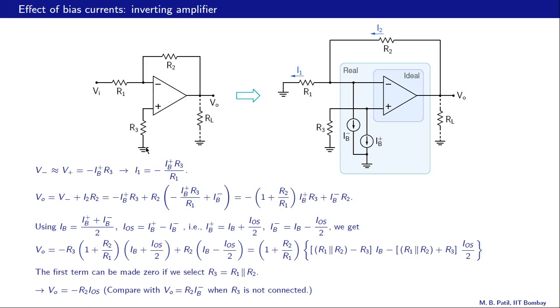We had connected directly the non-inverting input to the ground. So this is one trick that you will often see implemented in op-amp circuits, especially when the DC shift at the output is a concern.